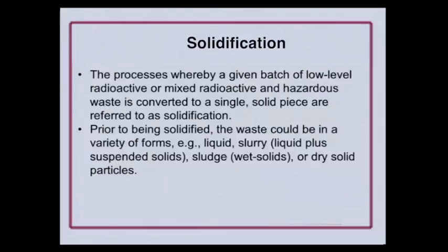Solidification, that's another process by which solids can be handled, but also liquids. Basically, you just take a batch of radioactive waste and you mix it in with concrete or some other solidifying agent, and you wind up with this chunk of radioactive material. And it will meet the stabilization requirements. We talked about this in 10 CFR 61 as far as stabilization requirements for the burial.